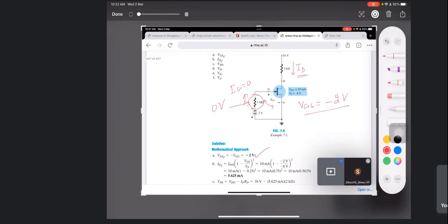okay, so this is the formula. This is given, so you can find out. Because I have given this and this, so directly from Shockley's equation you can find out. Right? VDS you can find out, VDD minus IDRD, quite simple.